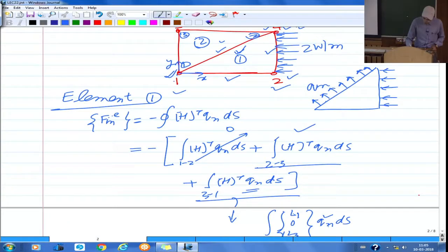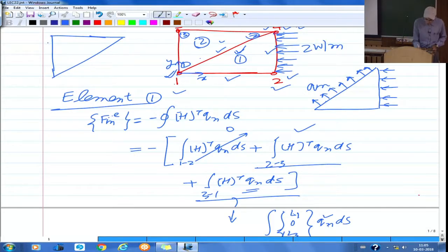And the integration when you do, the cyclic integration now would be from 1 to 3, that is 1 to 2 here, as you are going now for the second element. For the second element, you also look at the heat transfer taking place from the boundaries. This edge you are maintaining at a certain temperature, so let me for the time being say that there is some heat output here, which is actually an unknown, some Qn dash, which is going to vary along this edge.